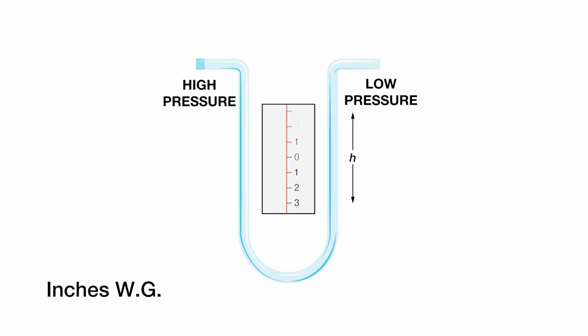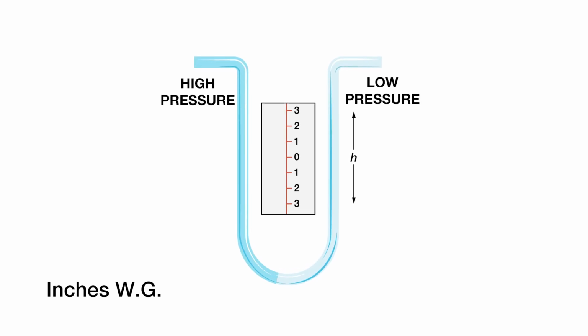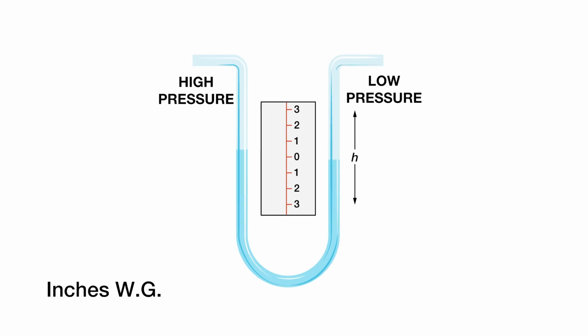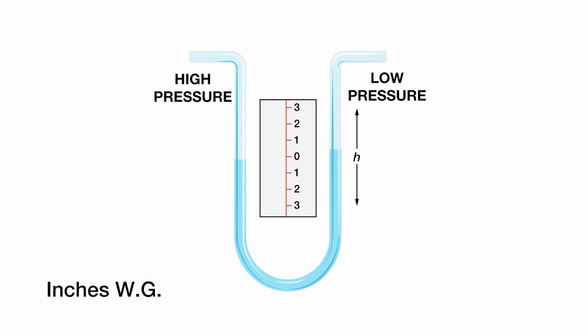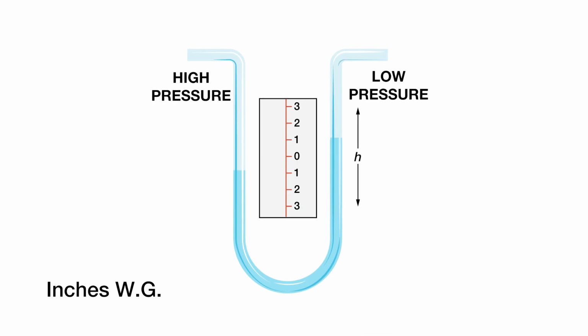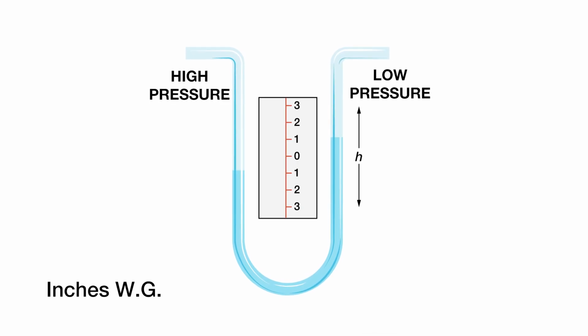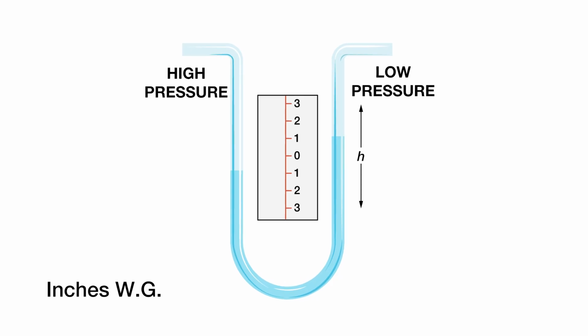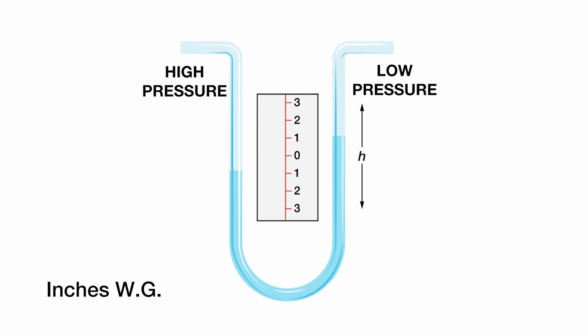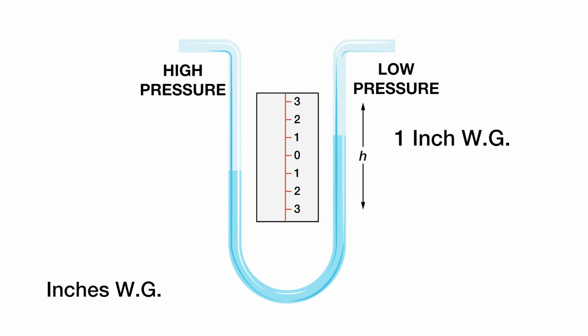That's because, historically, air pressure was measured before and after the filter by using a U-shaped fluid-filled tube. The pressure building on the upstream side of the filter would push the fluid down on that side, causing it to rise on the other. That rise would then be measured in inches, so if it increased by 1 inch, then the air pressure would be noted as 1 inch WG.